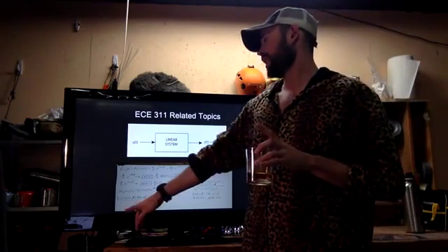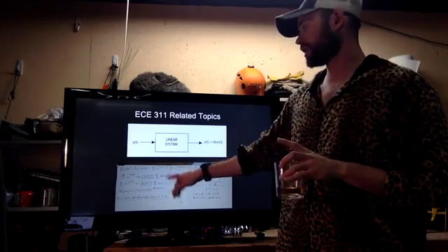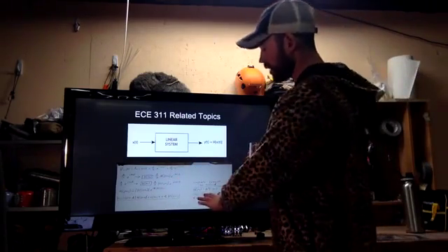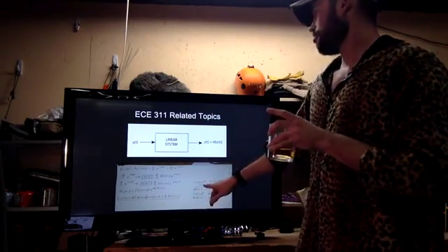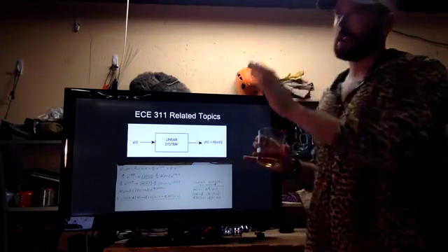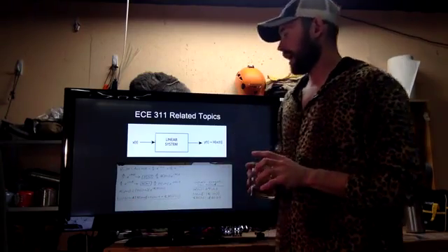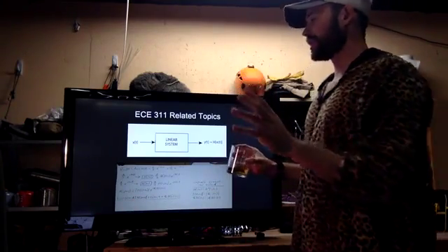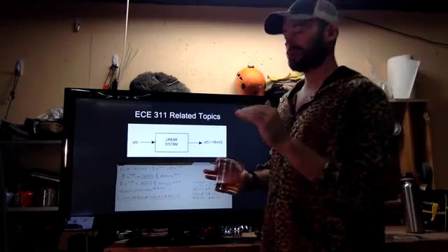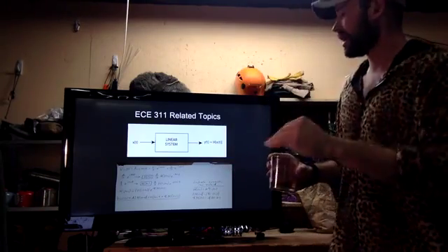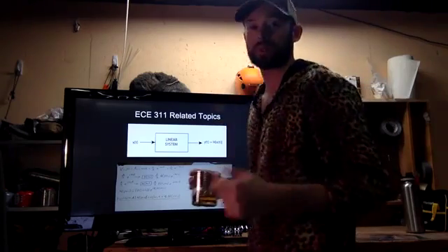What we're dealing with is two of these, but at different j omega naughts. One is positive, one is negative. However, because of conjugate symmetry, for a real valued input, we have h of j omega naught equals h conjugate of negative j omega naught. So the magnitudes are actually the same here. So we can pull this out front, and it turns out that the output signal is just a, whatever constant you want to multiply it by, times the magnitude of h of j omega naught cosine of omega naught t plus the phase. So there is a phase shift in our output.